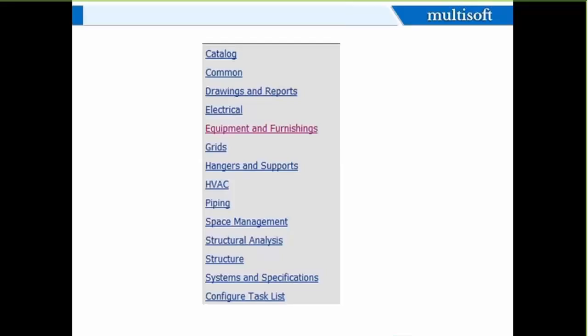Structural analysis is not an analysis itself; you can just give an input to STAAD, where they will do the analysis. You can apply live loads, dead loads, or uniform loads for your structure, and that can be exported to STAAD.Pro. That is again an engineering activity. But for the structure task, it's very good. You can place all your structure-related things like columns, beams, braces, handrails, footings, equipment foundations, ladders, slabs, and openings. Everything you can place in the structural task.